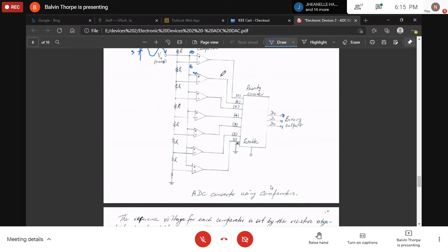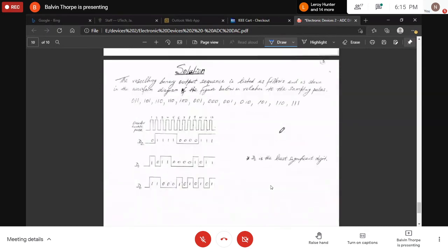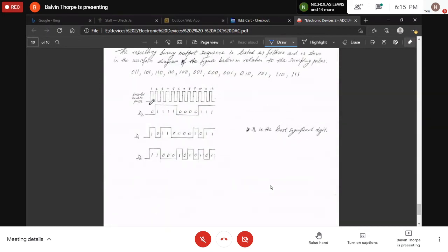But here it would be 0 because it's outputting a negative. Therefore, the highest value that you see is converted to the equivalent digital number. And 5, as we know, would have been a 1, 0, 1, which is what is done right here. See, for the second sample, it sees a 1, 0, 1.